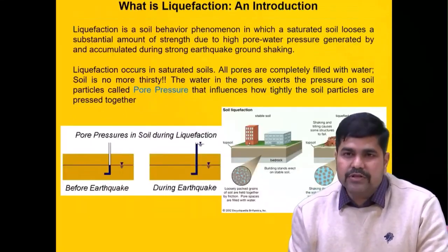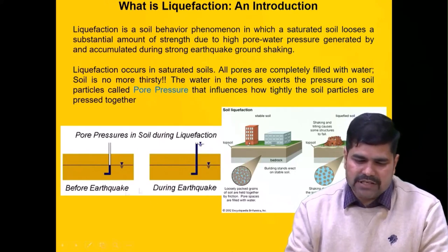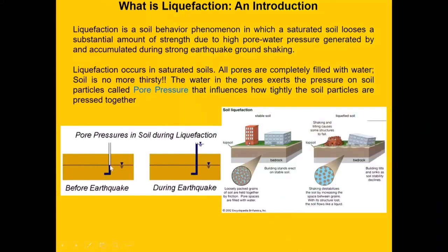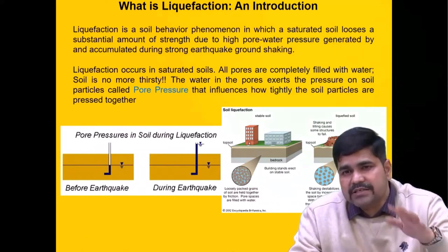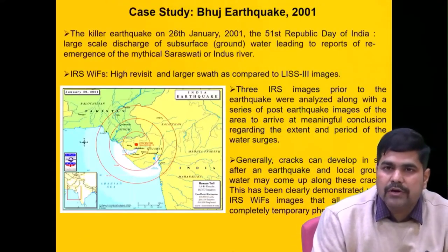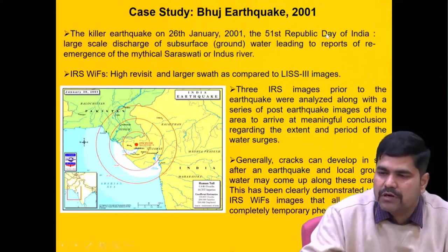I end with one example. That's what exactly I was discussing about liquefaction. This is your normal condition before the earthquake. Your groundwater is at this level, but after the earthquake, please see the capillary is bringing the water up to this level. That means all my pore spaces are now filled with water. Earlier these pore spaces were filled with air in this place. Now they are filled with water. So that indicates that my buildings which were earlier standing on sand now stand on water. That's how they will topple.